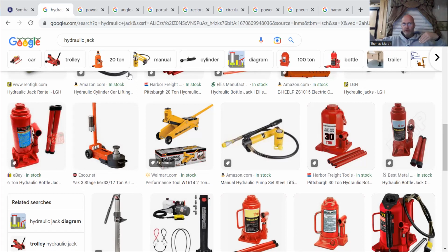I think it's like 22 inches wide and almost 30 inches long. You don't have the space to put all that information on that paper if you use imperial standard. So we use metric system, which means the scale must accommodate very large measurements. Each engineer scale is set up as multiples of 10, and the measurements are taken in decimals.